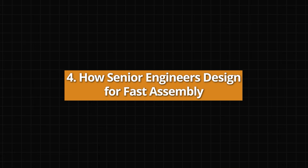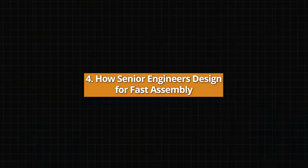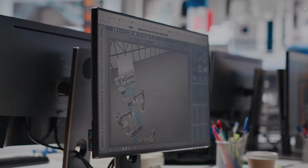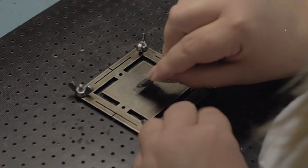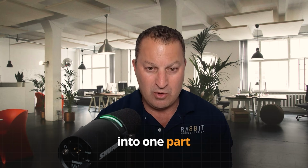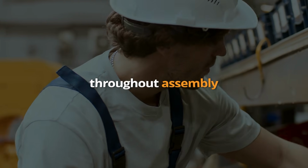Point 4. How senior engineers design for fast assembly. Experienced engineers approach design differently. They plan the assembly sequence first before detailed CAD work begins. They visualize how workers will build the product hundreds of times per day. Part consolidation is a major strategy. Combine multiple components into one part. Now you eliminate fasteners and reduce labor time. Standardized fasteners are another improvement. Workers use the same tools throughout assembly. No tool switching, no confusion.